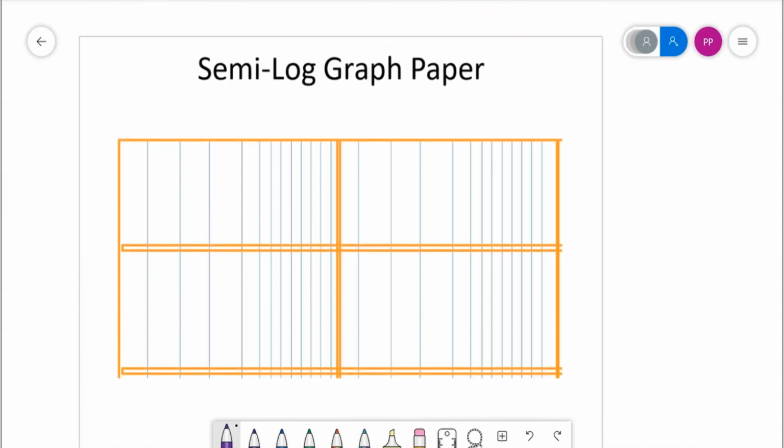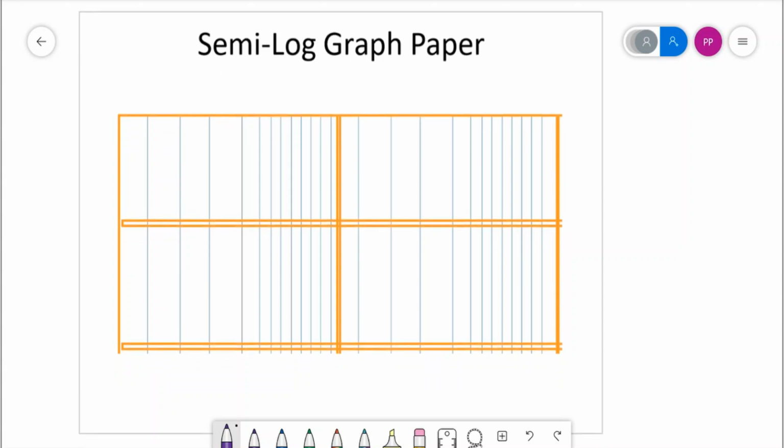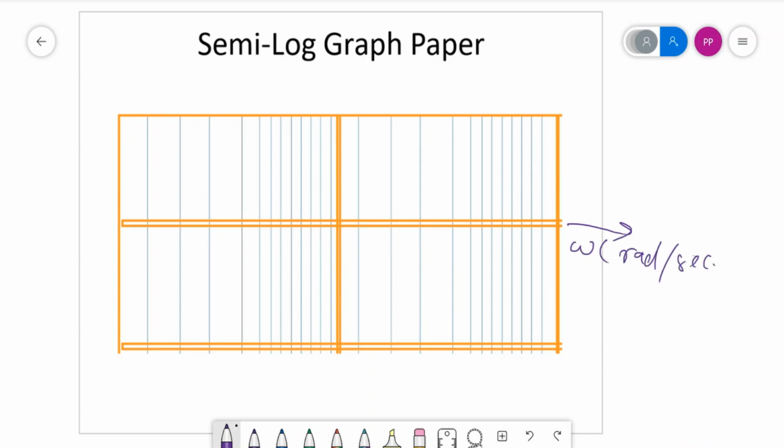When we are trying to plot it, we use the semi-log plot. Here you can see that these different bars are at uneven spacing. What we have done is kept the x-axis on logarithmic scale. The frequency I am using here is directly in radians per second, but whatever frequency I keep, it is automatically converted into logarithmic scale.